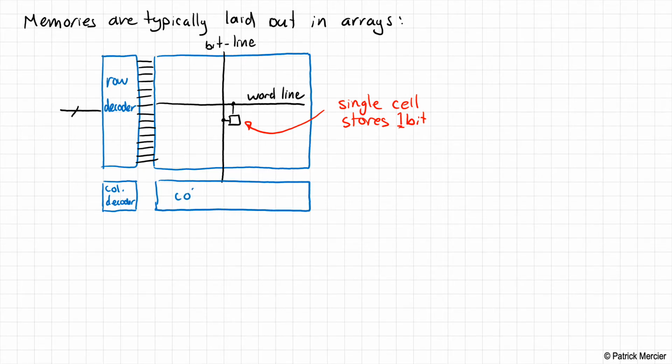These are our column circuits, and we'll talk about what goes into these column circuits shortly, but let's just assume that there's a whole bunch of columns in here. You know, this is a very big memory array. Okay, so what we'd like to do from the microprocessor's perspective is provide an n-bit address.